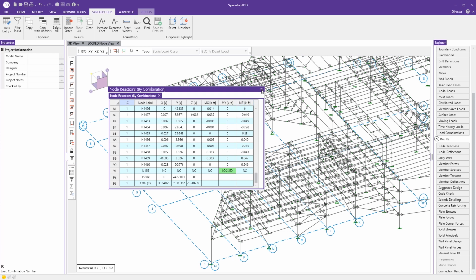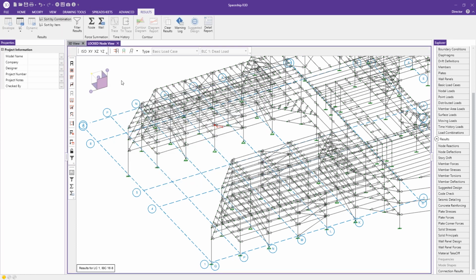So to look at that, I put my hand in the right hand rule direction, and I spin my fingers around in the Y, and I see that probably at N158, that lock doesn't mean anything. What is really happening is it's just spinning about its own axis, and that can happen sometimes in a three-dimensional modeling system. So there's a 0 running through the stiffness matrix, and so it's not real.